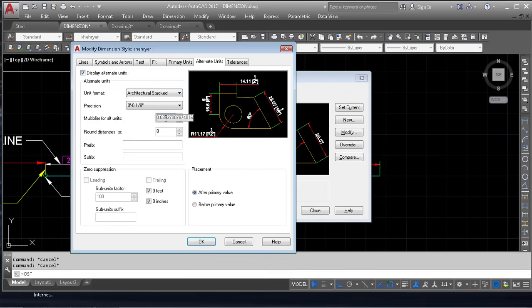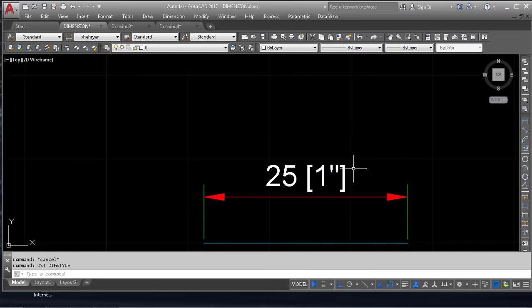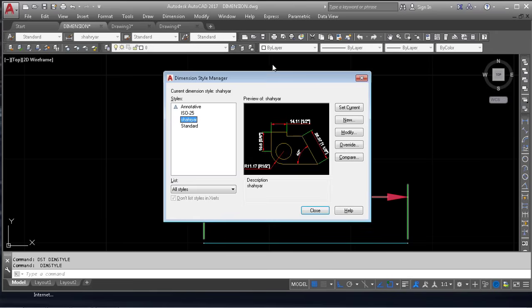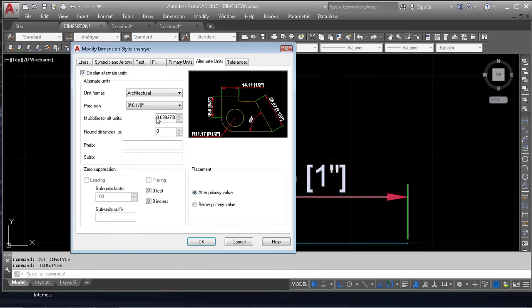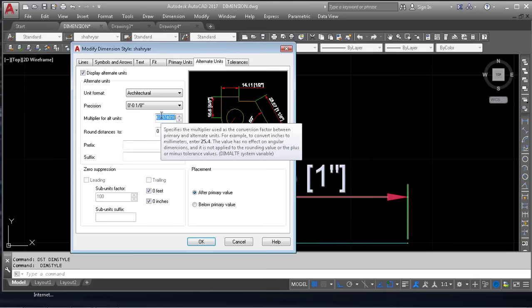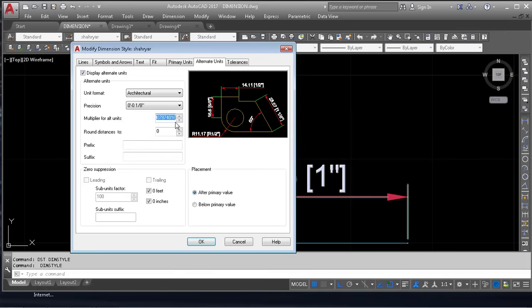as alternative you change it to architectural, and now we can see architectural, this one. Okay, now we can see it's around 1 feet 1 inch, but you need to see here, modify, the value is 0.03943, it's the conversion point. If you see how many inches are in 1 mm, then Google will show you this conversion point.